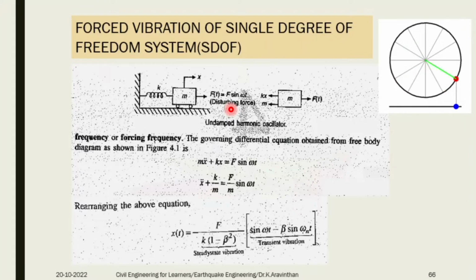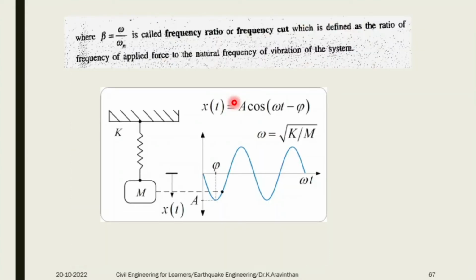And earthquake force. Does an earthquake continuously have the same shaking? No, it will increase in intensity and it can reduce. So it is non-harmonic. That has a separate equation. So you have the harmonic equation called F sine omega t. Why is the sine force introduced here? Sine, I told you in the last class. What do you mean by sine? You can plot the sine in terms of a wave.